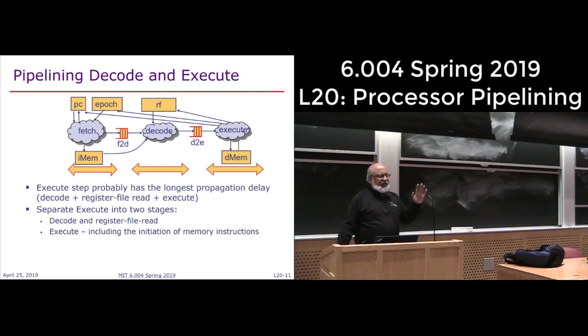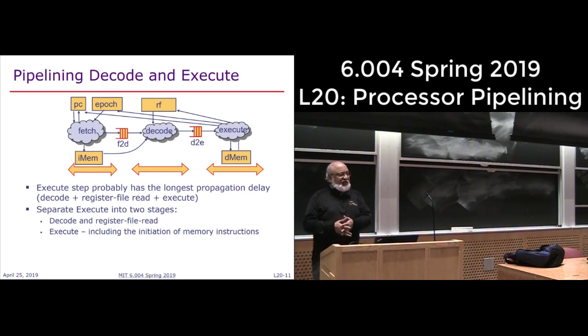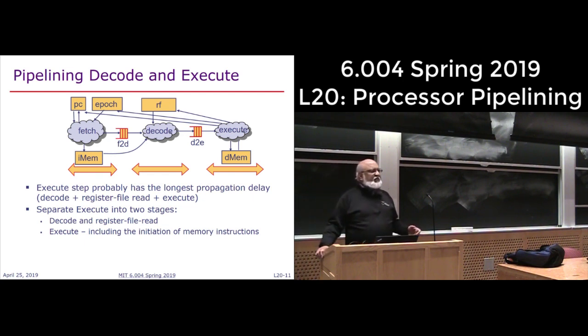So we have the fetch stage, which passes instructions forward. Until now it was 1 or 2 cycles after that, but now I'm being more aggressive. I'm saying, okay, we're going to split it further, decode stage and execute stage. Why? Because my combinational paths may get smaller and my clock speed may get faster if I do this. That's the reason for finer grained pipelines in general.